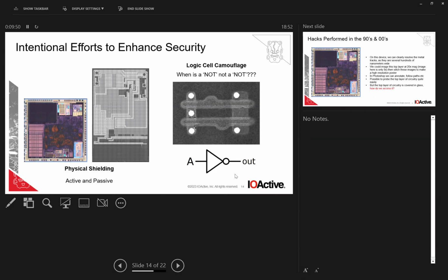So you clean that off. You can take that back. You can solder it back on your board. You can make it run because it still works. It's all connected. You haven't damaged anything. And you would run it, and then you could put a needle on any signal you wanted, and you could just basically listen to the data. So this is what people were doing for a long time, very successfully.